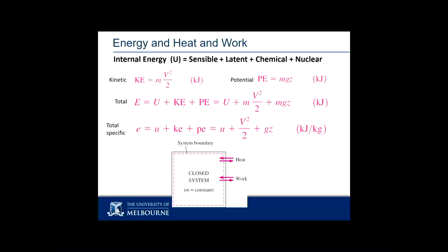So, we said we had system boundaries. We said they could be closed or open. In the closed system boundary, I can't transfer mass. All system boundaries, I can have heat transfer across unless I tell you it's insulated. But also importantly, all system boundaries, we can transfer work across it. If I couldn't, we really wouldn't have that many problems to analyze. Either I couldn't get work out of a system or I couldn't put work in to make a change. So our system boundary has two portals through which I can make a difference to it.